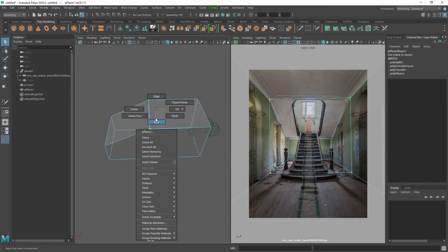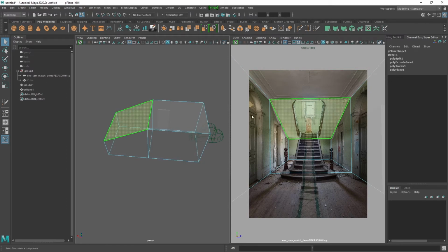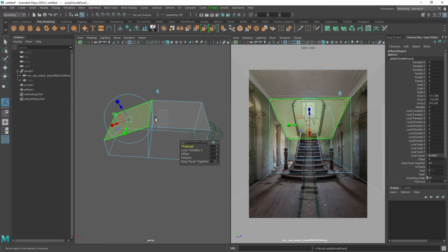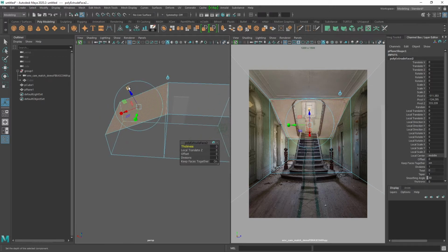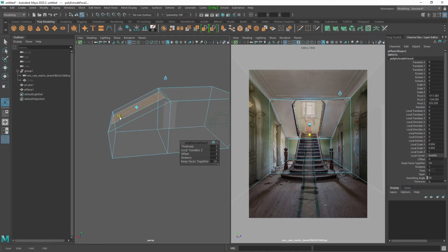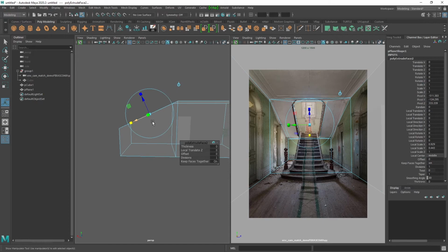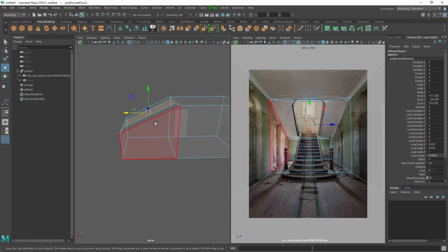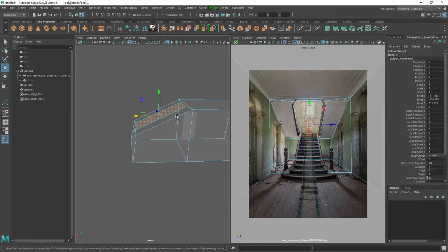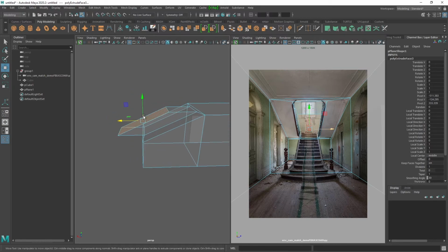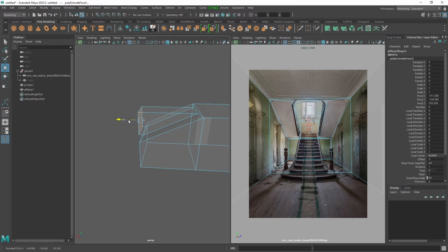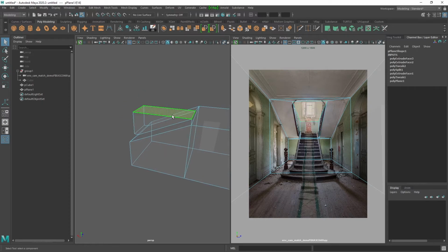And then now what I can do is start to do this cutout here. So I can do Control E again, just a nice extrude. We can do this scale in on a couple different axes, and we're going to just do this cutout here, and then I can do G for repeat last and just move this back, right? Now this isn't entirely a modeling tutorial on this environment, but I'm just showing you how I initially roughed this in.